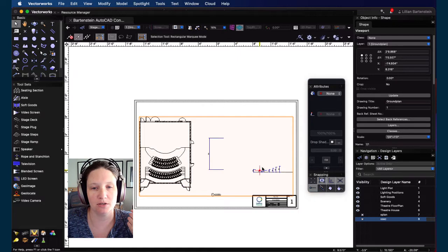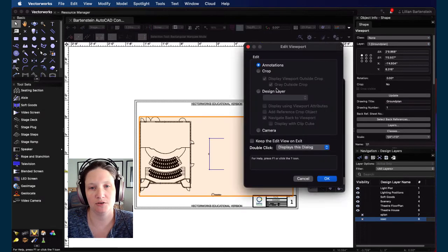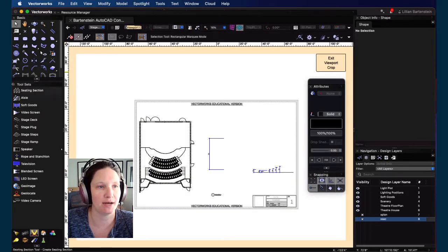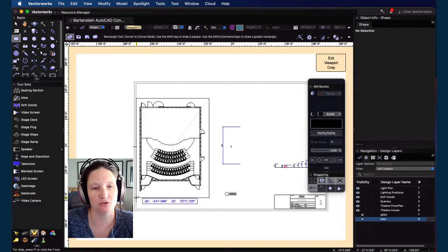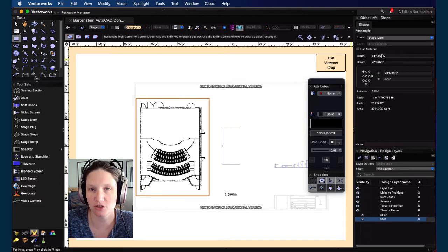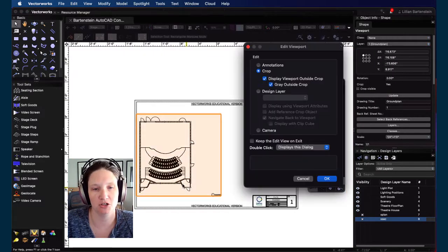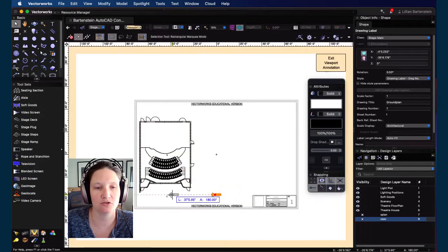So what you'll notice is a bunch of stray business came along with it, okay? And for the purposes of our adventure, we're just gonna crop that stuff out. If you wanted to be much cleaner about it, you could go in there and actually delete those dimensions so that there's nothing on the design layer. All dimensions should live in a sheet layer, okay? So I'm also moving my drawing label underneath the drawing, okay?